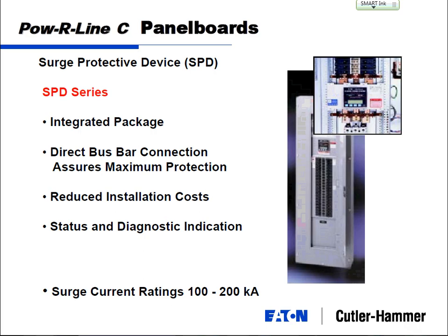So large spikes that are very quick. They're tough to see. They don't really do any damage to normal stuff. They're invisible on a motor or a receptacle that you're plugging a hairdryer into. You ain't going to see much of a difference. In solid state equipment, transient voltages can actually damage a TV or a computer and cause it to fail.